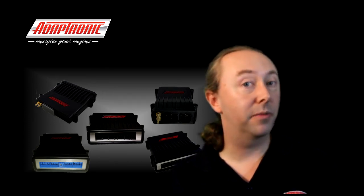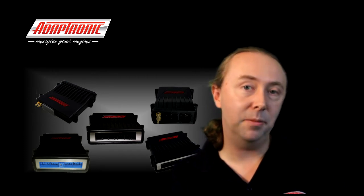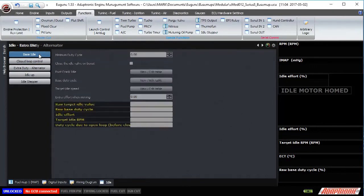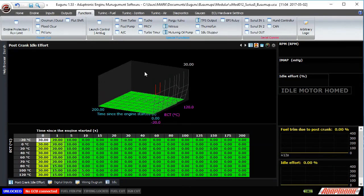And in practice this works really well, and much better than having a digital input to tell you whether an input's on or off. Now the final function that I want to talk about is the post-crank idler. This is a table with coolant temperature on one axis and time on the other, so time after cranking. So t equals 0 is the point where the engine first fires, and then 5, for example, is 5 seconds after it started, and so on. The maximum time that you can do this for is 5 minutes, so 300 seconds after the engine starts. But in practice, if you need that long, then you're probably doing something wrong.